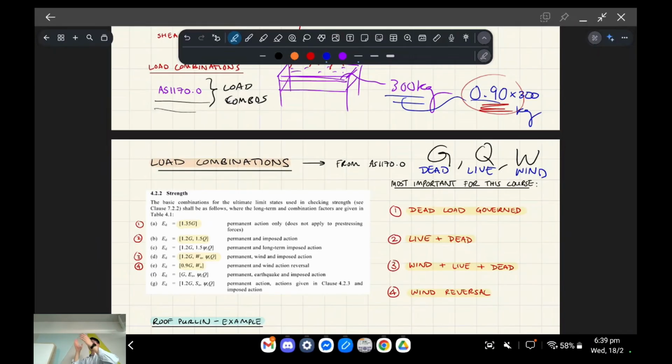A live load might be a human or a car or something that's going to move from place to place. It could even be this whiteboard that's on wheels, because it can move around. Live loads are free to move around, and so we want to factor and treat them differently, because live loads can vary more than dead loads. I'll answer your question in a second.